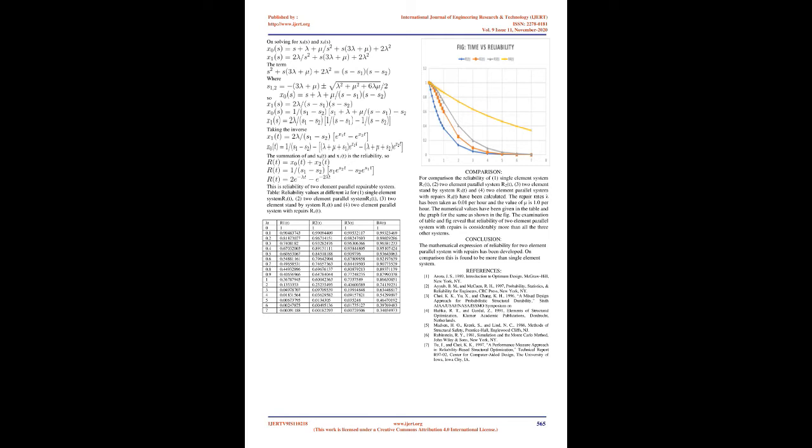C. Steady state availability, or long duration availability. This is applicable to those systems which are expected to work continuously. This is again the ratio of the cumulative working period of the system to the total time in which the system is expected to be in working state. Mathematically, the total expected time is considered as infinite. In reality, it would be large. Steady state availability A(∞) equals working time divided by total time T. Examples: thermal power plants, scanning radar system, etc.